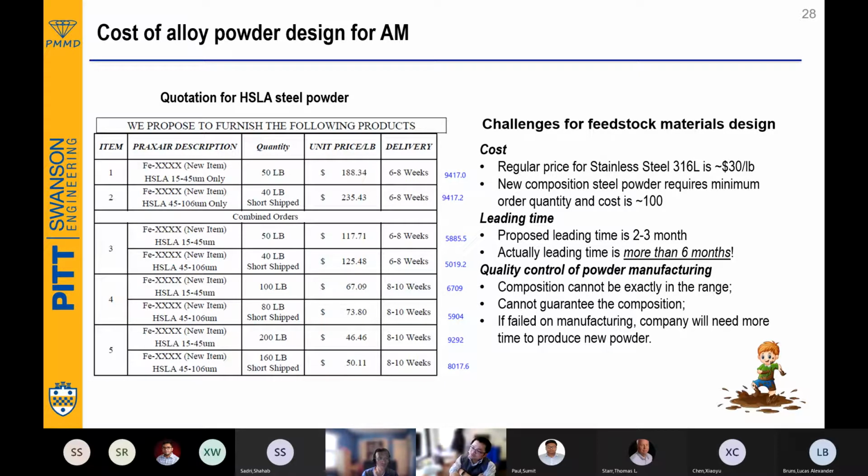Before you do additive manufacturing, you think, oh, this is really eco-friendly, environment friendly, right? So you just bring the powder and do the printing. No, if you choose the powder, you have to make sure that the powder is easily processable, and then printability is good, right? So we do 316 is okay, 718 is okay, right? Everyone is doing this, but now HSLA, no one knows. It's good for welding, we know. Then you can move forward with additive manufacturing, right? So experiencing some of the similarity with the thermal history.